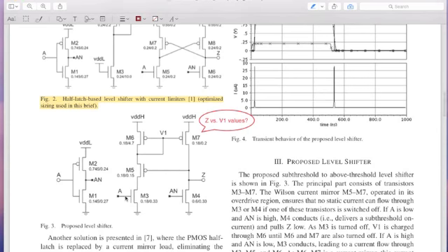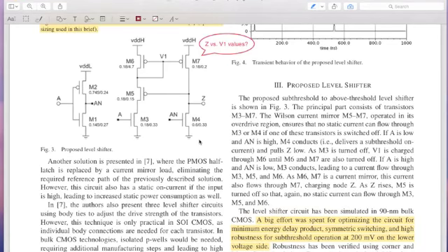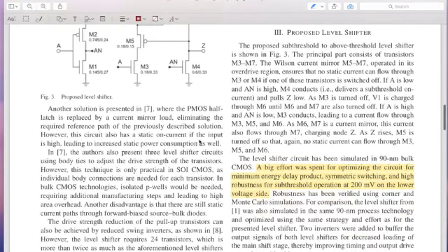When this M6 limits the current through the M5, what that does is it helps M3 to overcome M5. And also the way this is set up, once the system stabilizes and reaches its logic values, there are no more static currents out here. Okay, so you can just go through that and see how that works.